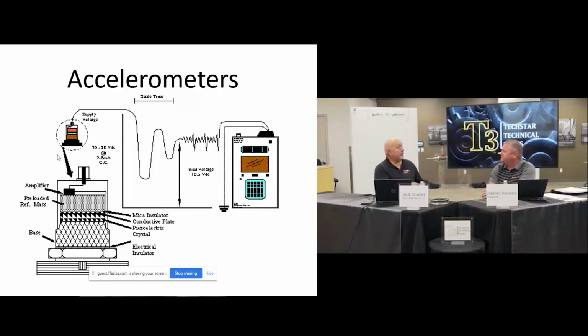And then there's other types of probes you might consider if you're going to use, let's say, enveloping or peak view, spike energy. They have what's called more of an ultrasound probe that you can also use, a little more defined on the higher frequencies.